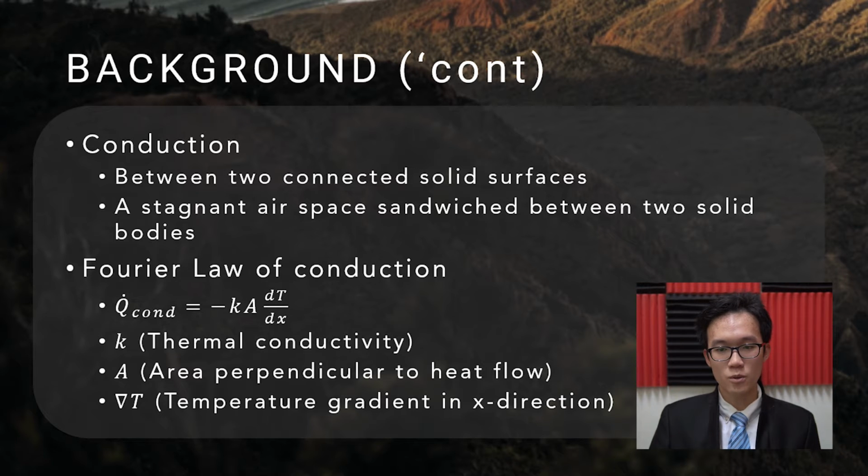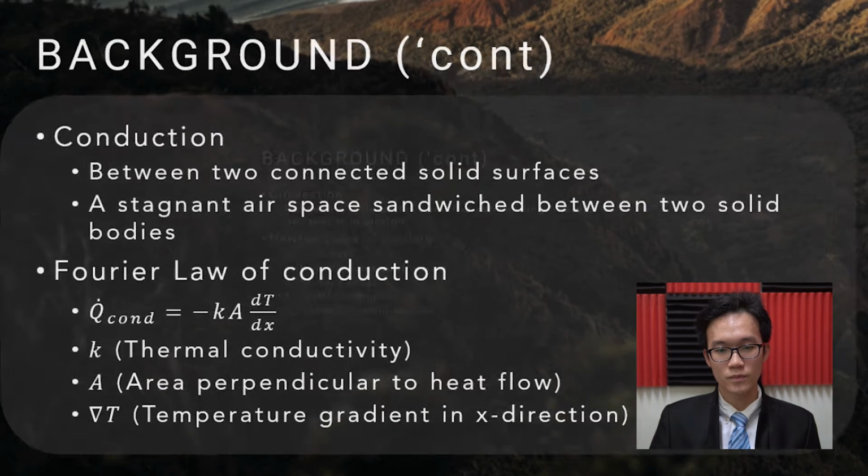To solve conduction problems, the Fourier law of conduction is applied with the equation shown, where K is the thermal conductivity, A is the area perpendicular to heat flow, and delta T is the temperature gradient in x direction.